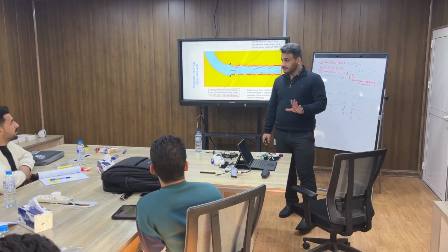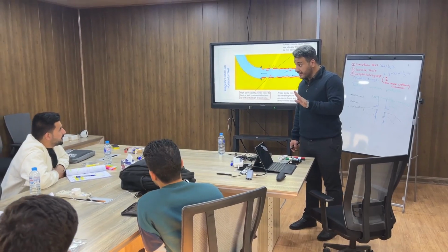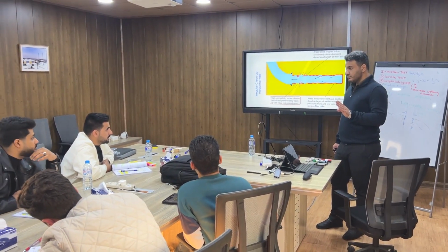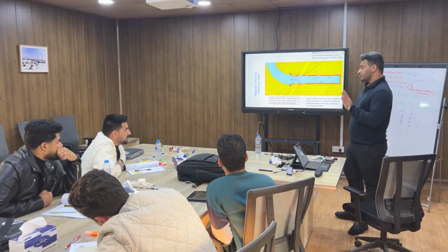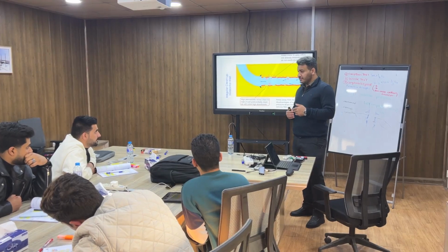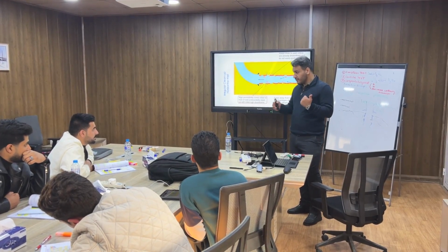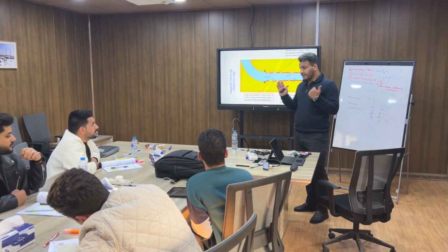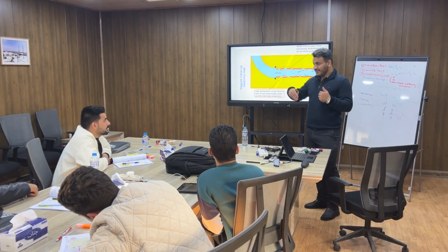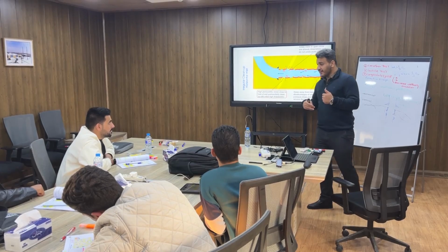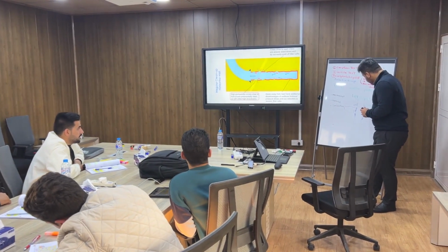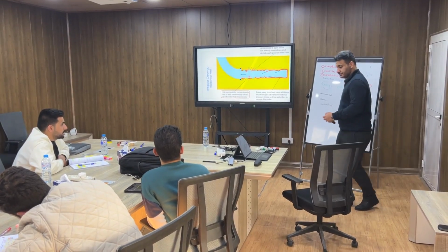How do we mitigate this problem? For example, a big fracture? Yes. A small amount of loss of the drilling fluid is controlled by adding the LCM to the drilling fluid. But in the harsh condition, we ask the coil tubing service company to come to the rig and inject the cement, so the fracture is filled with the cement.